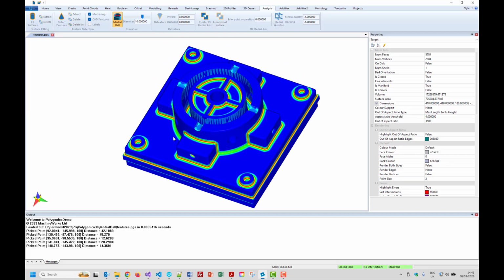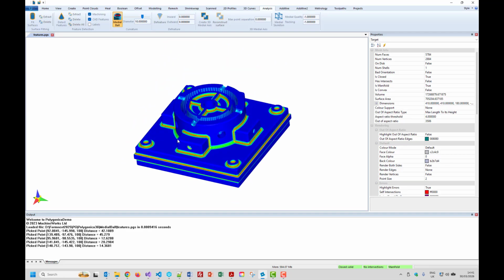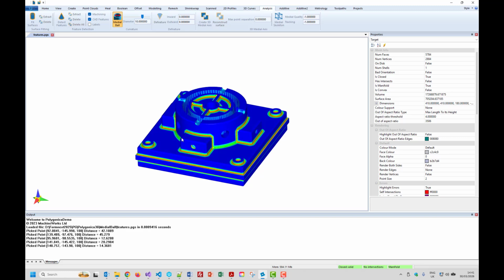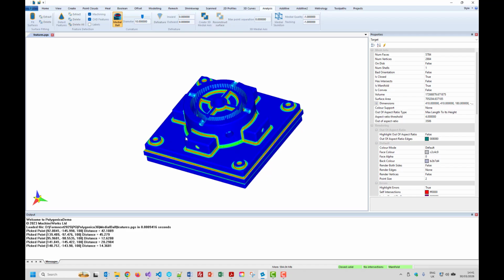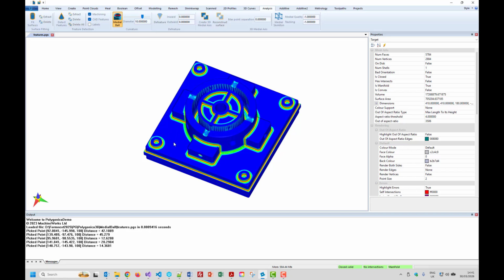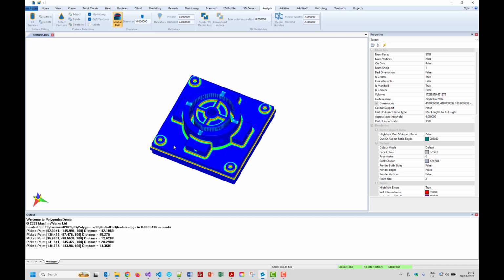The other thing I'll say also is that the algorithm has callbacks, so it works based on a faceted mesh, but it has callbacks that allow you to feed in information from the CAD BREP surfaces if you've got them. So that can help increase accuracy. In effect the algorithm will say, well, can you tell me information about the CAD surface in this area? For example, tell me the exact point on the CAD surface and the normals, etc. And then it will use that as part of its medial ball calculation to give a more accurate result than you can get from the faceted model.